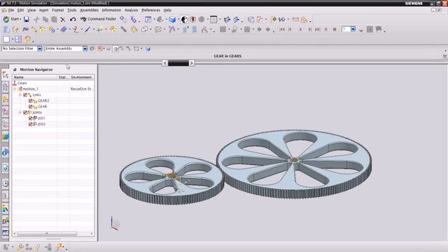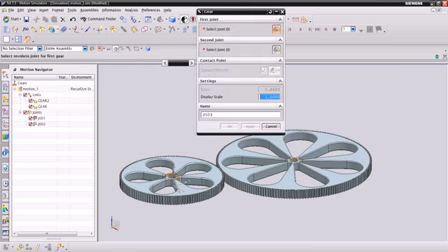With the revolute joints correctly defined, we're now ready to define the gear coupler. Click on the gear icon again, and now select the first and second joints in order. The critical piece of information in the gear dialog box is ratio. What you would like to enter here is the ratio of one gear's radius to the other. Now, we have expressions in each of the gear part files for the radius, more specifically the diameter, but we're going to need to add a slight perturbation term for the size of these teeth.